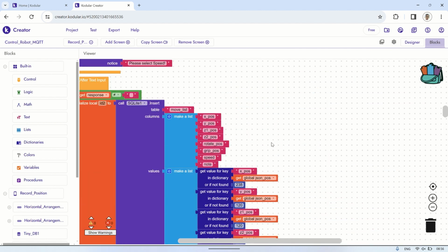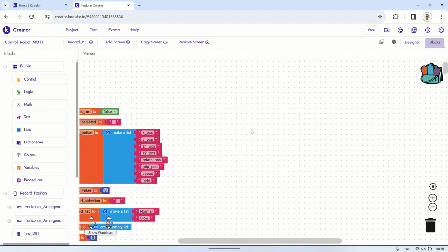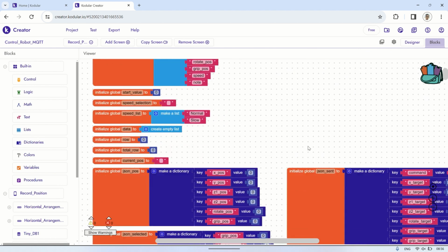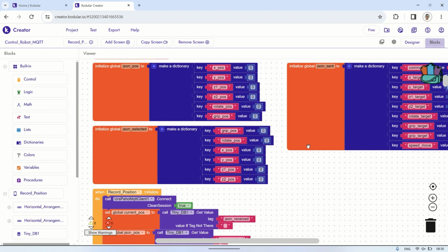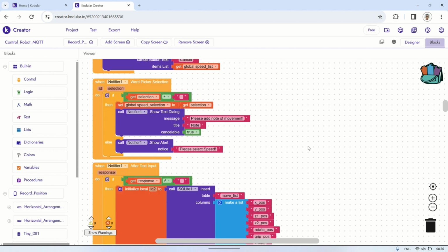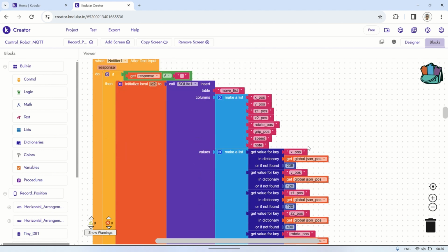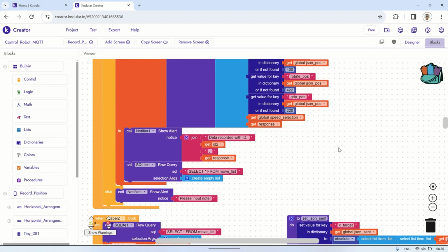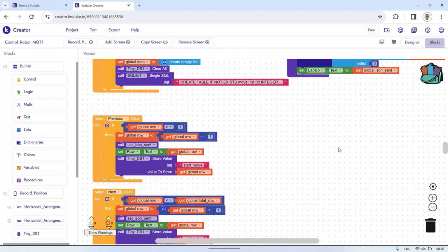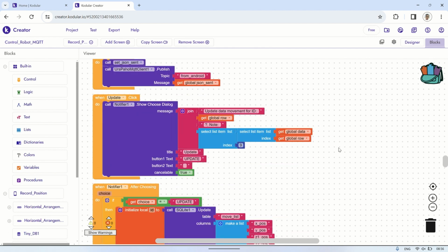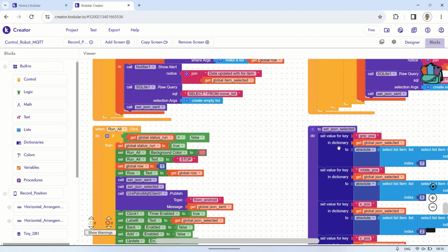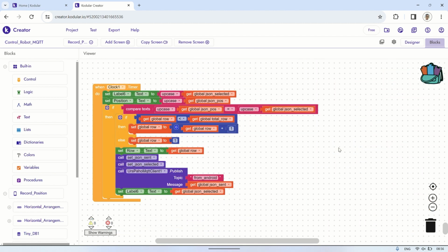This block code is used to save the value of each servo position to the database and execute it. In essence, when the robot is manually moved, it will send the current position of each servo. Kodular receives this message to save the positions by pressing the Add button. The data is then stored in an SQLite database, including its speed. To execute a movement, Kodular sends a JSON message with the command move and the target positions for each servo. When receiving the move command, the ESP will operate each servo according to its target position, and then send back the current servo positions.